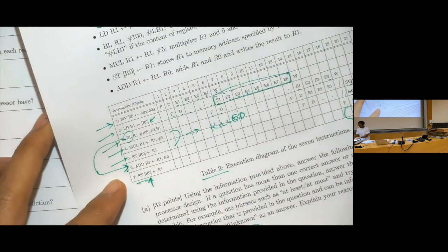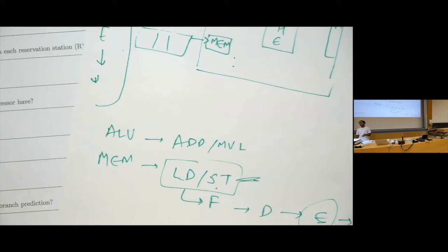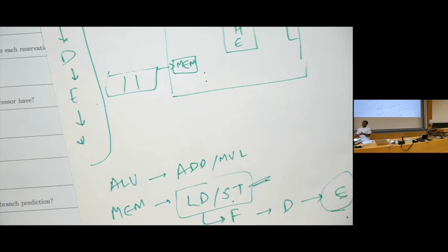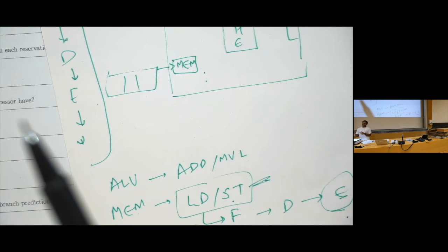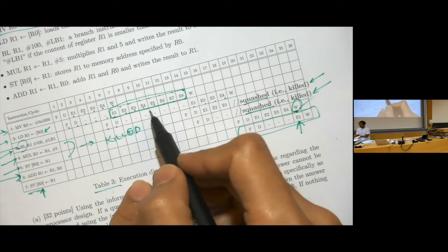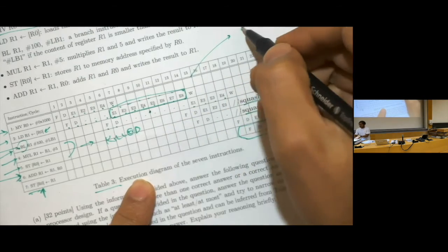So the first question that we have is, what is the cache hit latency? If I say cache hit latency, immediately your mind should come to, oh, cache would be somewhere on the load store path, right? And we saw that we have load store instructions for the same address, which had different access latencies. You remember, we clearly identified that there was one instruction accessing the same memory address, another instruction accessing the same memory address, but this one took 8 cycles.